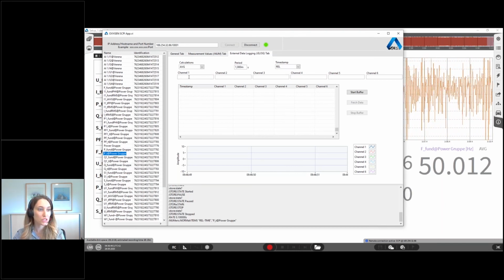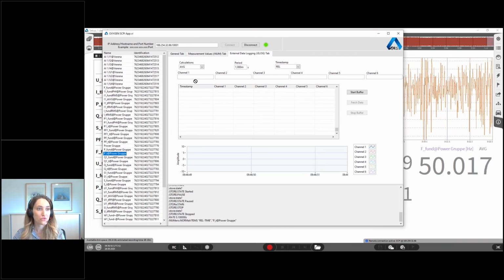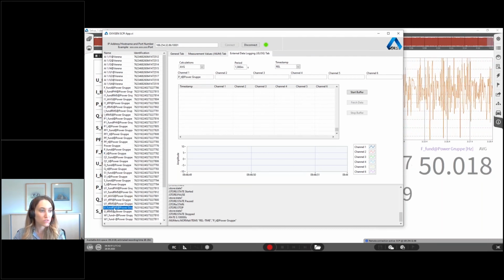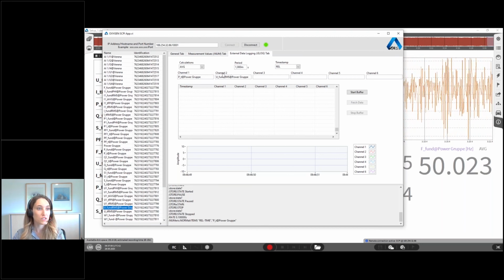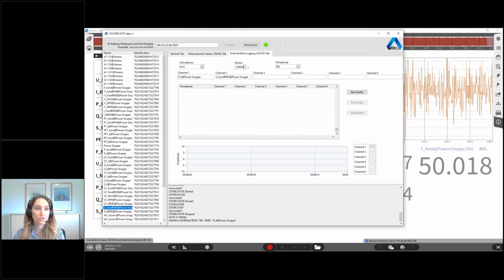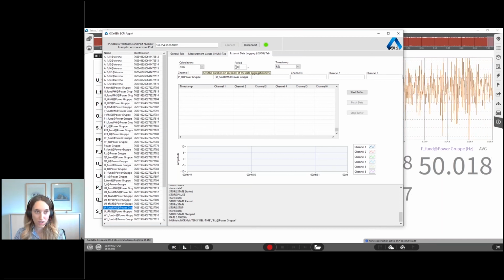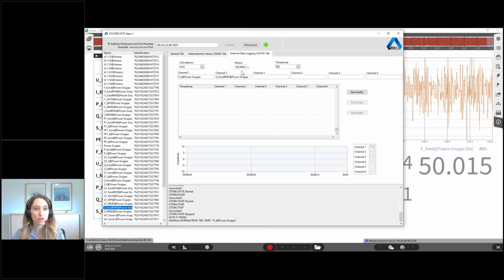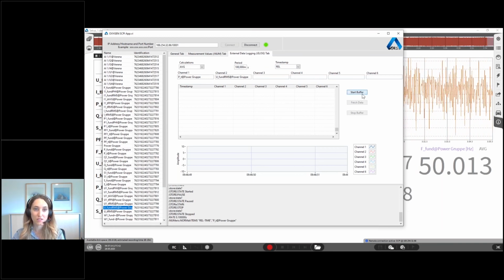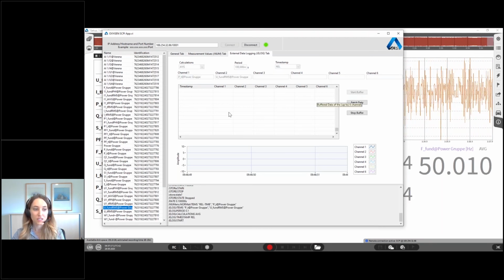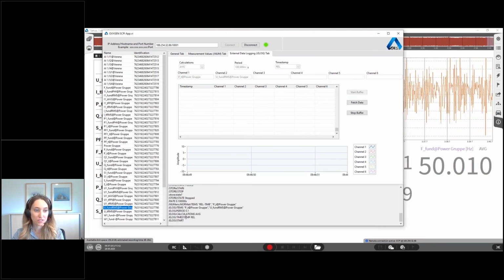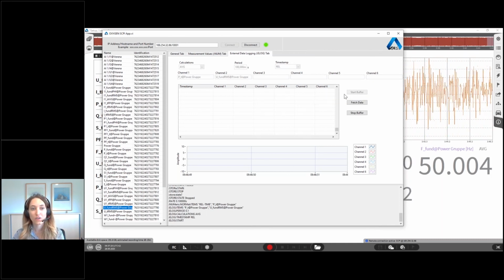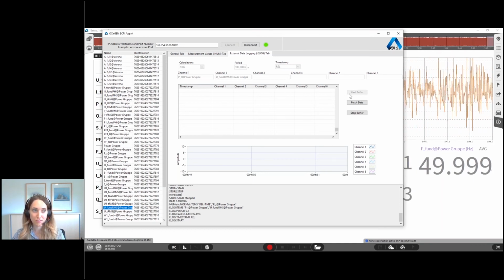So in order to do so, we can again drag and drop desired channels up here. So we also use the voltage fundamental RMS value and calculate the average over 100 milliseconds. Okay. And then we'll just simply click on Start Buffer. As you can see, all these settings are set here and are executed, but we cannot see any data right now since the values are only saved into the buffer now.